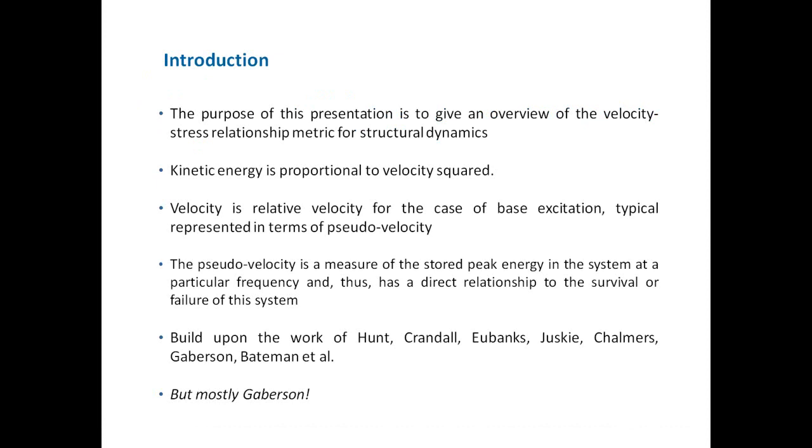If you remember back to your high school physics, you learned that for a rigid body in translation, the kinetic energy was equal to 1/2 mass times velocity squared. So we can say that kinetic energy is directly proportional to velocity squared. So velocity then is proposed as being the best metric for characterizing the energy stored in the modes of a vibrating system. Now when we talk about velocity for the case of base excitation, we're really talking about relative velocity.